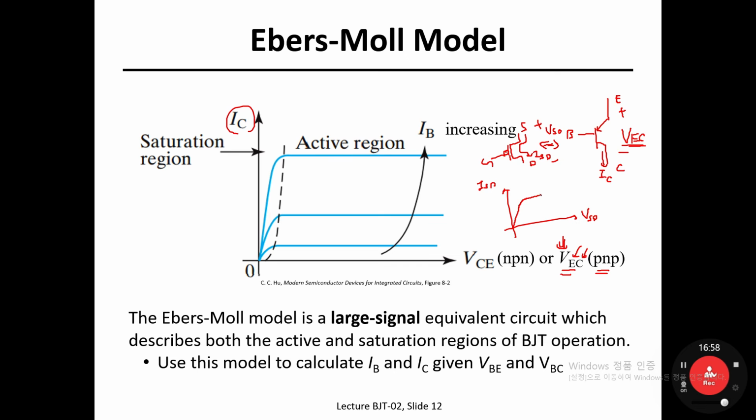You know this, right? In MOSFET, in P-type. Since this is P-type, if I'm using the real polarity, then usually the x-axis is VDS instead of VSD. So the current is formed in this direction. That is the real one. But since source and drain are switched, the real measured data has been drawn in the first plane instead of the third plane. All right, and well, let's go back to the Ebers-Moll model.